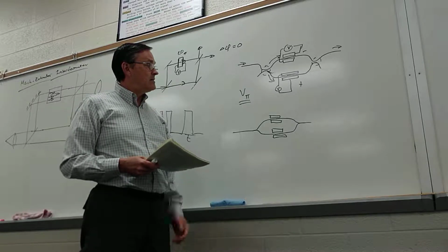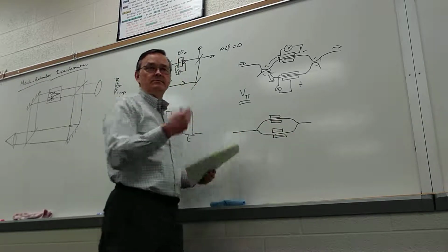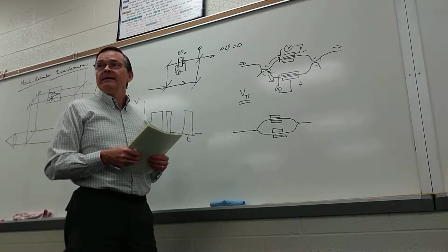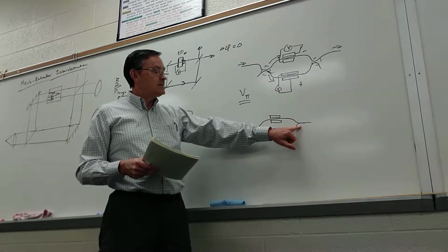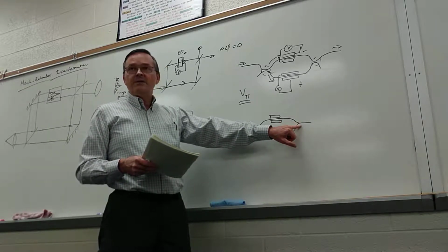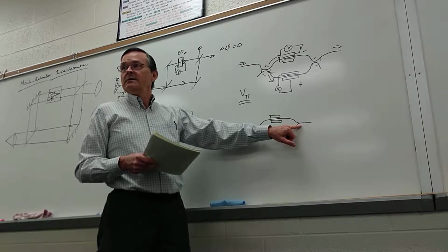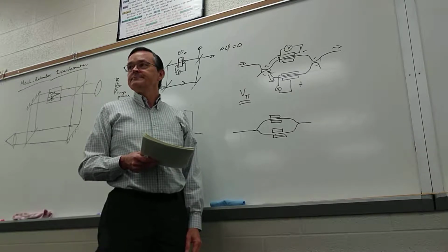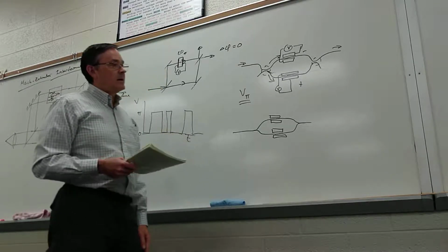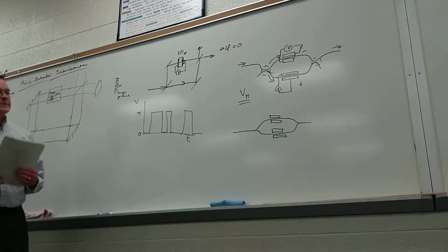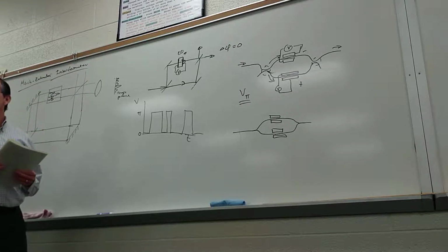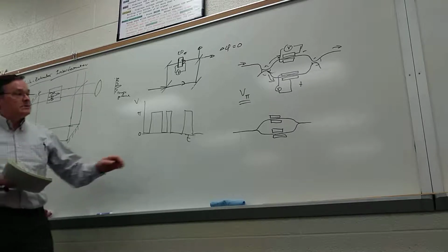Well, it turns out that it can't reflect. There's no mechanism to reflect it. But it has to go somewhere. And so it turns out the other port is unconfined light. Namely, it just leaks out. It just sprays into the substrate. So, yeah. And so you probably want to have a way of attenuating that light by making the other surfaces of the chip absorptive or something. So that's really how it's done.